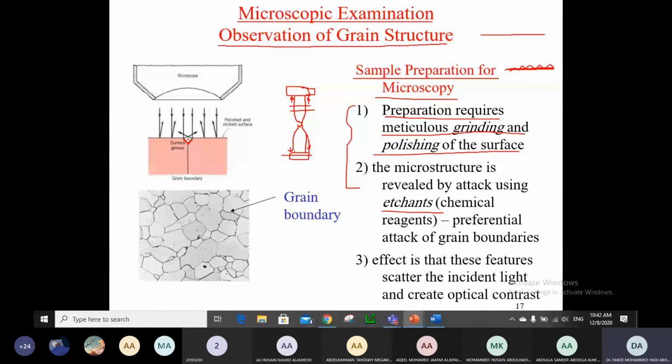Why is the material eaten faster here? It is eaten more because the atoms are much more energetic there. They are much more chemically reactive. So this forms channels at the grain boundaries. Like grooves, I mean. They form channels at the grain boundary. This is within the grain, and this is at the grain boundary. It causes the development of those channels, if you want to say.